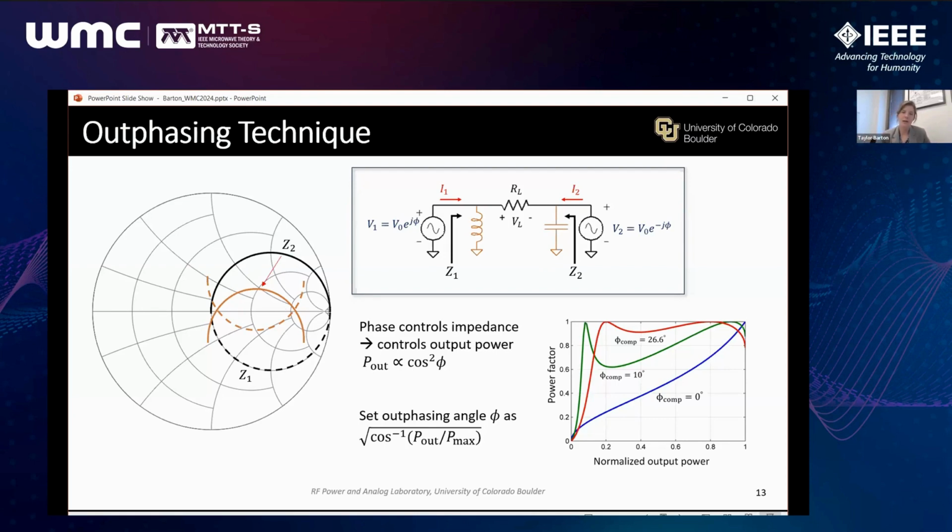And you can choose here to trade off more dynamic range and resistance, which comes with more imaginary part to your load, or you can move the lines closer together and get a smaller dynamic range, but a broader, more resistive loading overall.